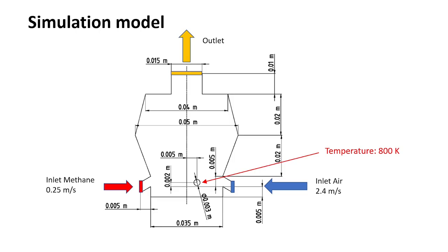Normally, when you take a look at other simulations, you find that the total volume will be heated up to 2000 Kelvin or something. In this simulation, I changed this, and the simulation space will only have a temperature of 293 Kelvin. So this is a normal temperature, but we will use a hotspot with a temperature of 800 Kelvin. So this will lead to the ignition of the flow.